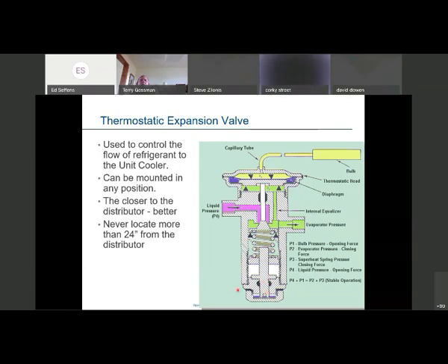I used to have a rule of thumb. 10 degrees was pretty good. When I was with Sporlan back in the 90s, we used to throw out 10 degrees as a good rule of thumb number. But if you take into consideration the lower your suction temperature is on the evaporator, you could drop that down quite a bit, actually, 6 degrees, sometimes even 4 degrees superheat. The less superheat you have with the expansion valve, the more refrigerant we have feeding the evaporator, and our efficiencies go up.